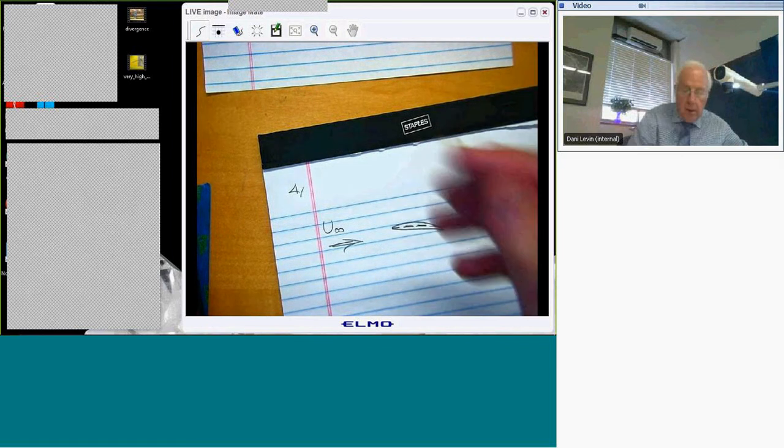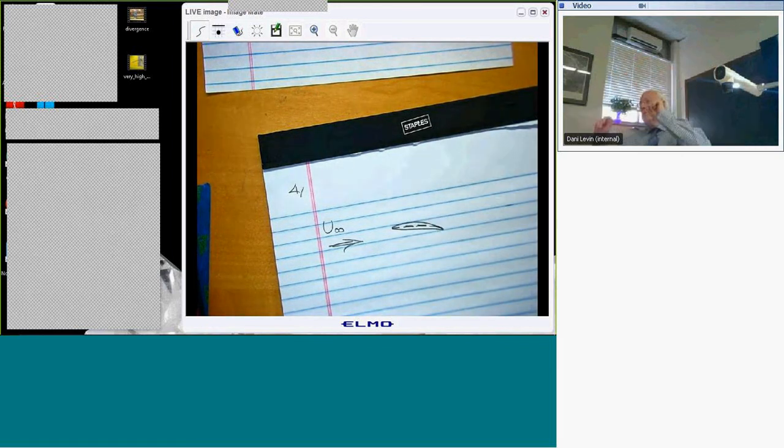But the actual thickness I can assume is 0 because the thickness, according to linear theory, generates a perturbation pressure that's the same on the top and the bottom, therefore the net is 0, so I can forget about the thickness. But in supersonic flow, that's not true. Excuse me, in transonic flow, that's not true.